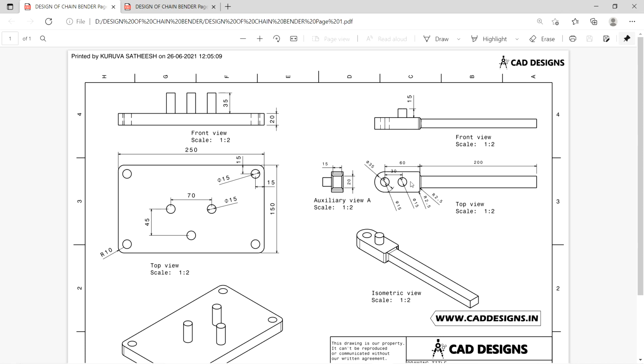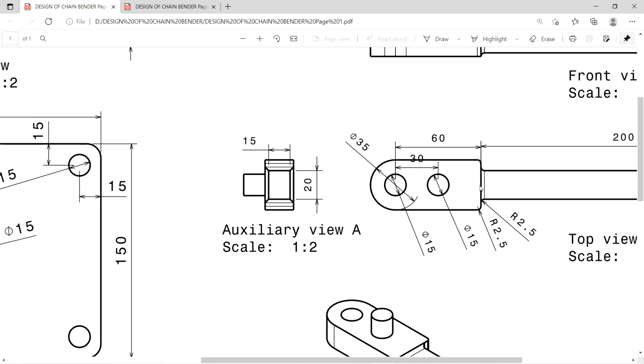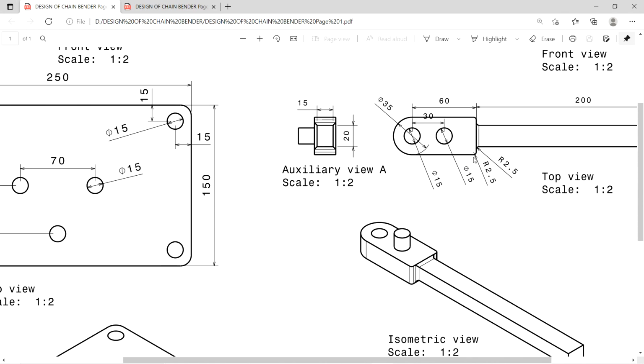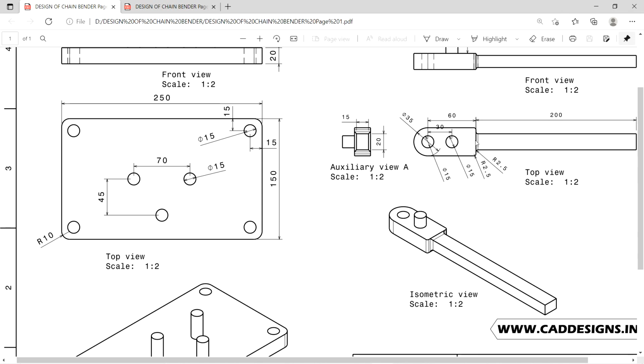Here we have one hole. And after creating this base, after that create this cylinder. Now first I'm going to choose these dimensions. See what this rectangle size is. This one is 35 diameter, so it means half of the value. First create this 35 diameter circle and next create this rectangle shape also, that is 60 mm distance. And the next one, we need to maintain some distance for this one also. So what is the distance? That is 35 diameter. It means this is also 35.